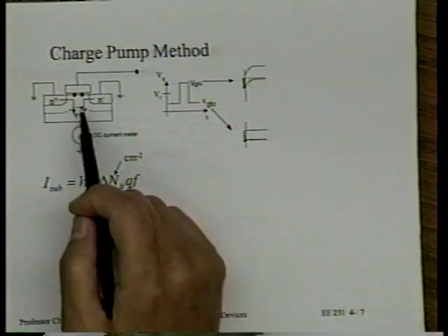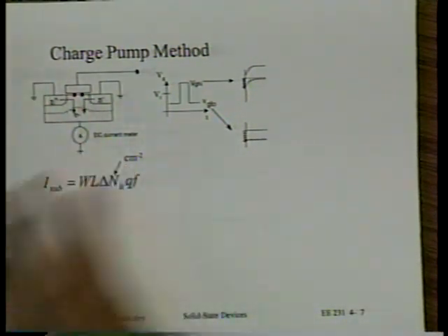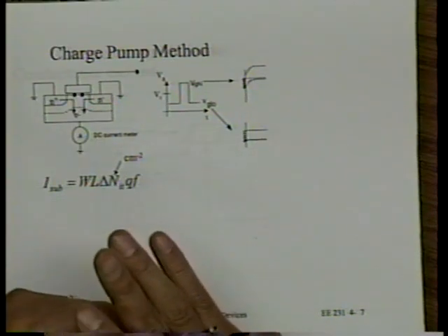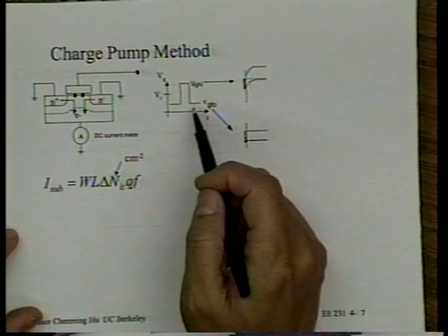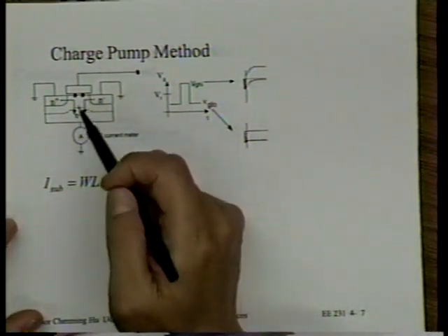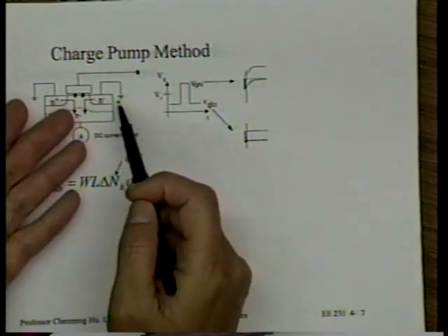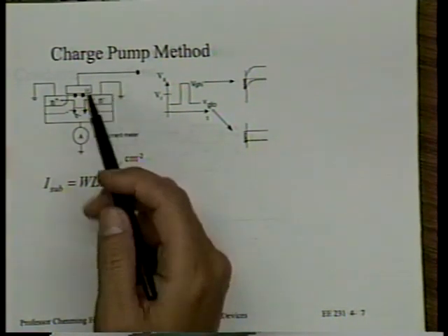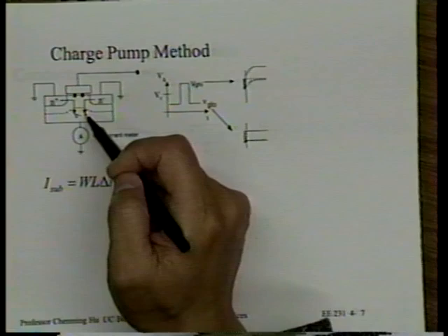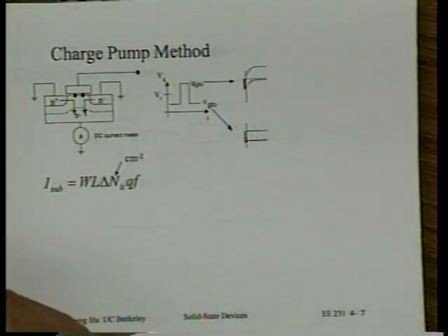On the other hand, the inversion layer should have already totally disappeared, very quickly after we move to this point. So at this point, electrons come out. Where do they go? There's no inversion layer for flow between source and drain. So some of them will just flow into the substrate.